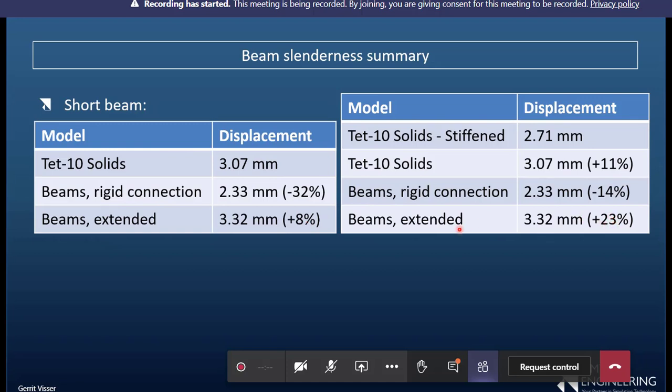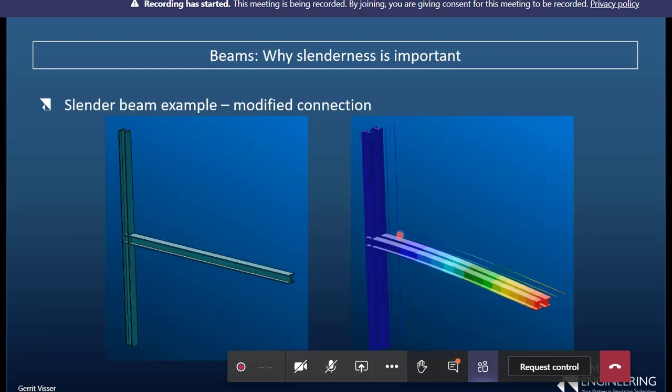Okay, now why did it over-predict it? If I go back again, that material for the beam that I added there has got stiffness. So as I apply that load, that beam already bends. So effectively, I'm adding in series a stiffness. If you add spring stiffness in series, you're reducing the total stiffness.